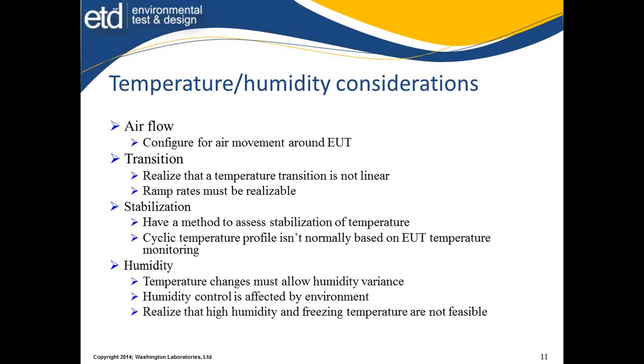Humidity control can be affected by the environment. We shouldn't believe that we can get 5% humidity when it's the middle of summer in the tropics or some other place like it, like Florida, or in our case, Maryland. This humidity out in the environment will affect our ability to achieve some things. So consider that when we're doing the test, that we may have a limitation and not have that same limitation in another time of the year.